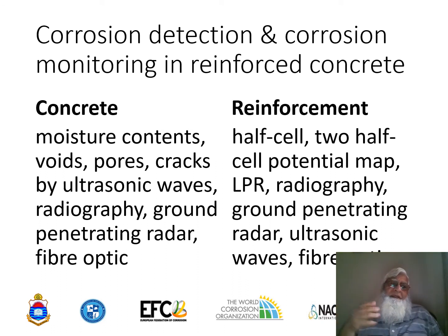And then concrete radiography, ground penetrating radar, ultrasonic waves and fiber optics are used for the same reason: to find out the location of the reinforcement, the structure and profile of the rebars, and any corrosion profile of the rebars.